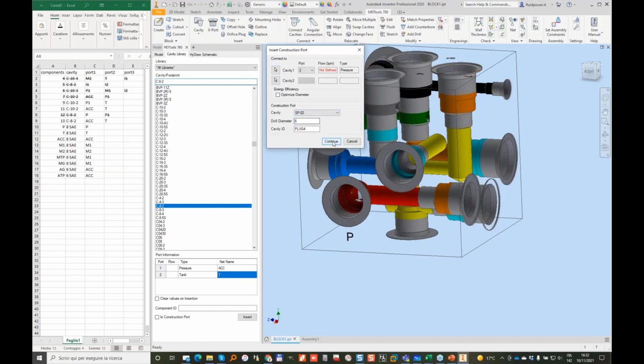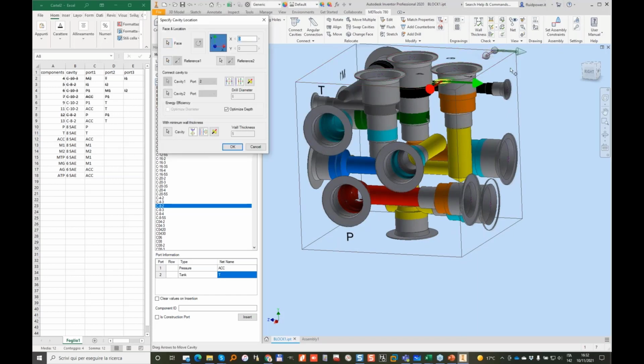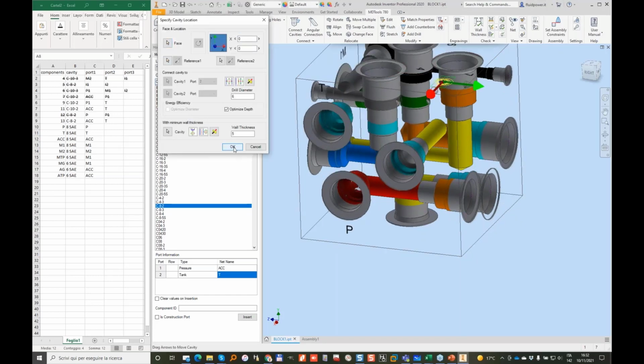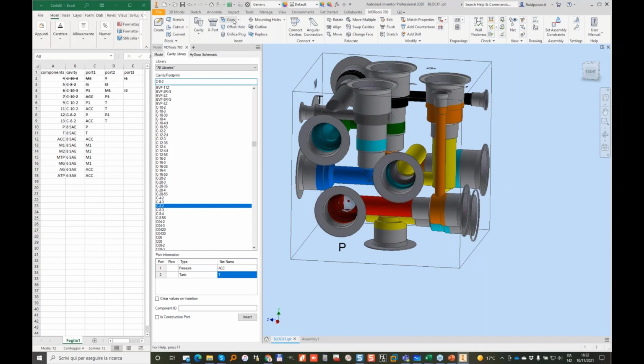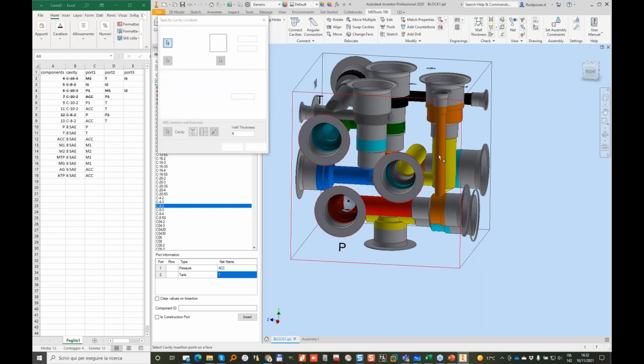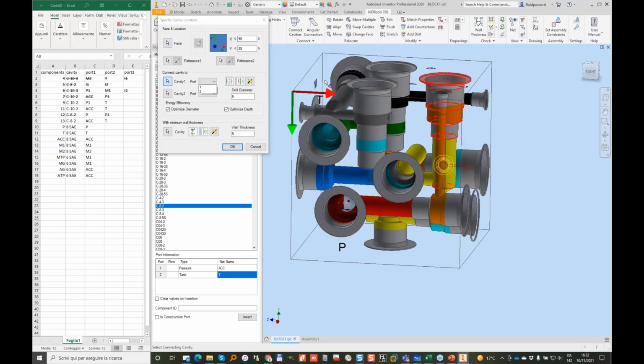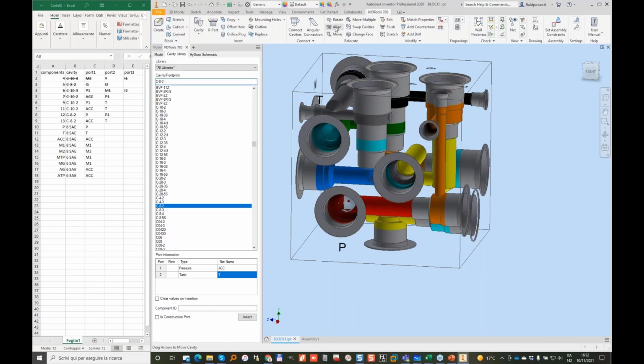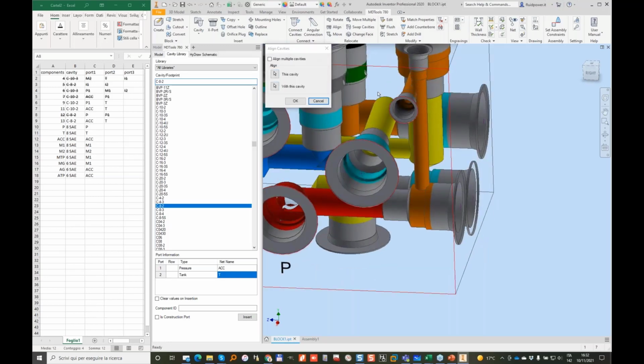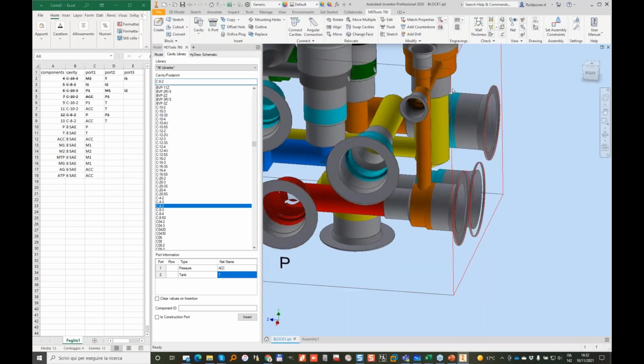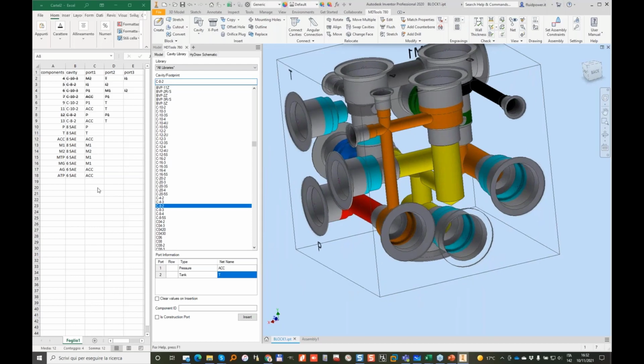I always take a small plug and put it on top face. And then I copy the same plug and connect in the orange, port number 2 with port number 1. And I want to align these two so that they are center to center, and it's easier to machine them.